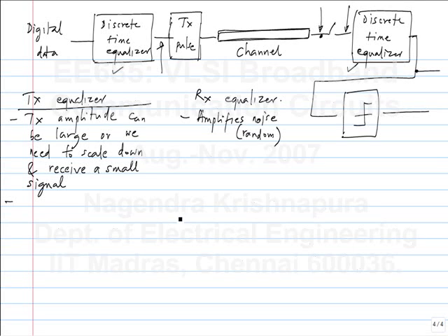Basically, you want to see the samples. We have not said how to do adaptation and so on. But in a perfectly equalized channel, what do you see? If you sample it, you will see either +1 or -1. Those are logic levels that can correspond to some voltage level, say plus 300 millivolts and minus 300 millivolts. You look at the samples; if they're all the same value, then it's equalized. If not, it's not equalized. So you don't need any other reference. You can do blind equalization. You just look at the analog values corresponding to the received symbols, and if they are not all the same, that's not equalized.